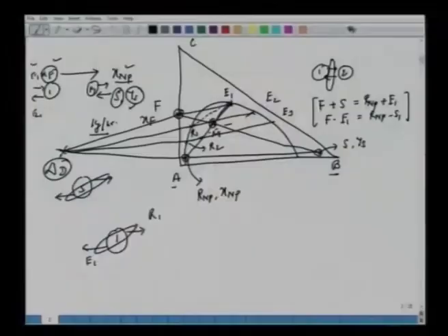Now to determine the minimum amount of solvent, we have to see the condition when the operating line, which originates from del D and intersects the equilibrium curve, becomes parallel to the tie lines, or coincides with the tie line. When it coincides with the tie line, the driving force for mass transfer is 0, and we require an infinite number of stages for the separation. So we locate that del D min, then we take the operating point at 1.2 times or 1.5 times.